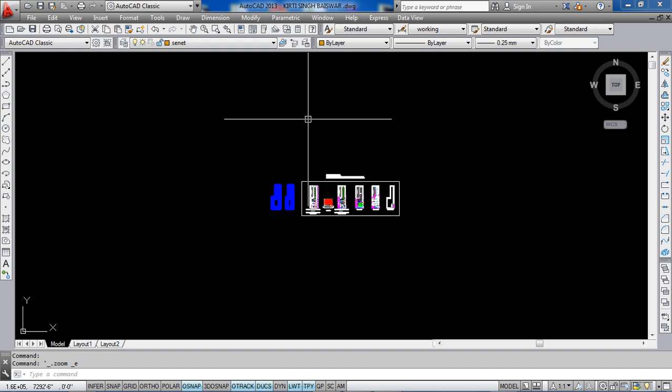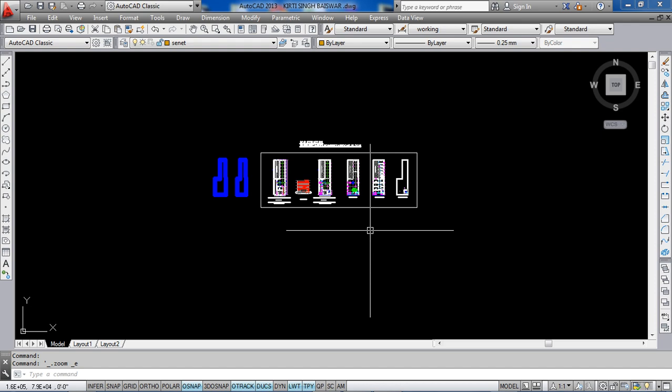As all of us know, we receive the drawing from the architect with several level plans, and we also know our STAAD modeling is done with a single line for beam and column. So we have to export the single line plan of AutoCAD into STAAD.